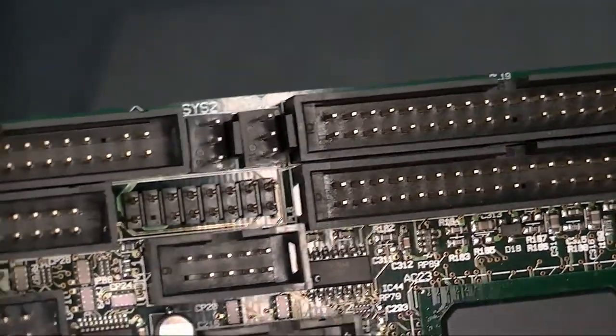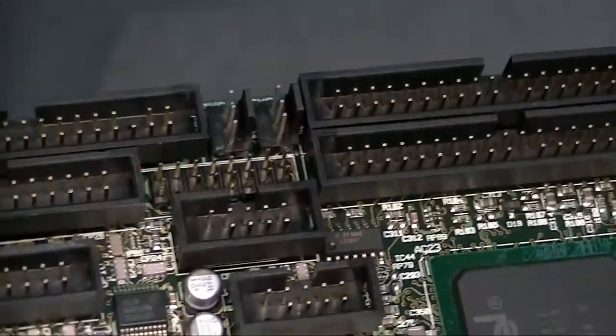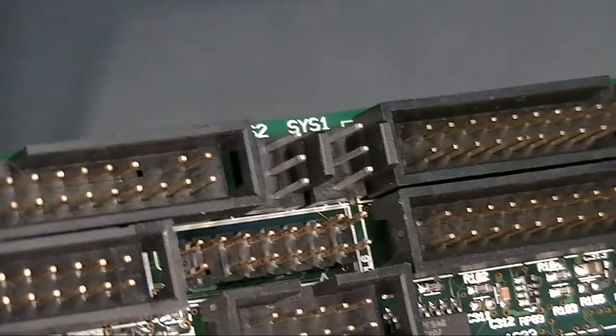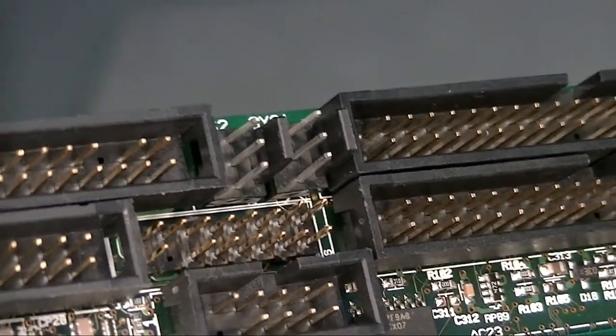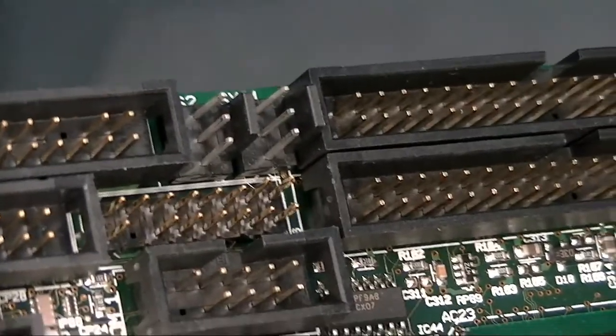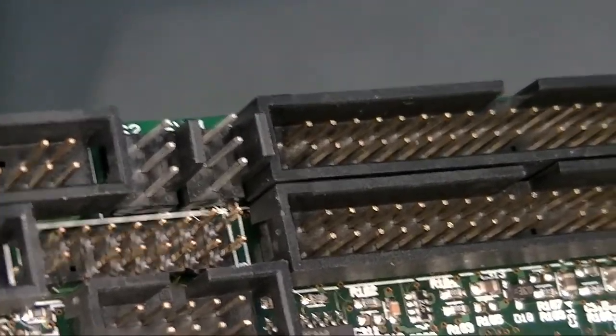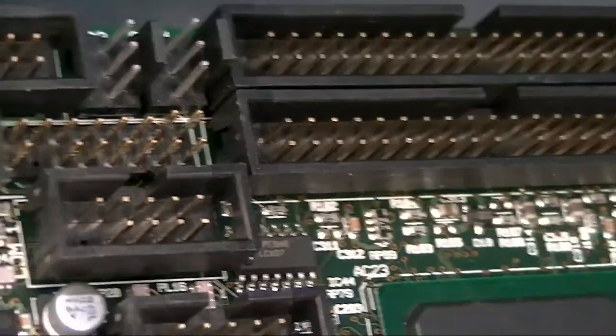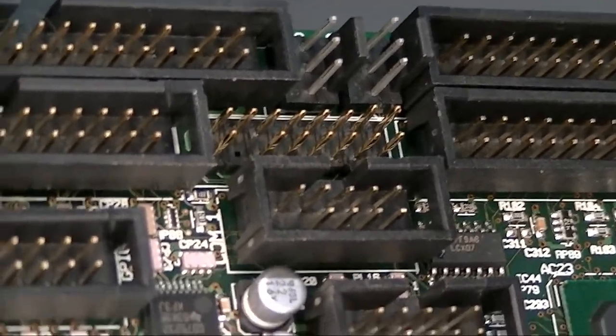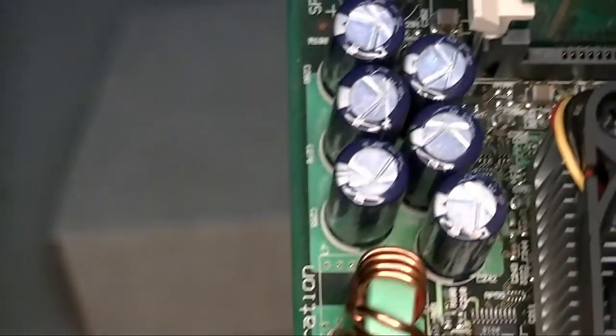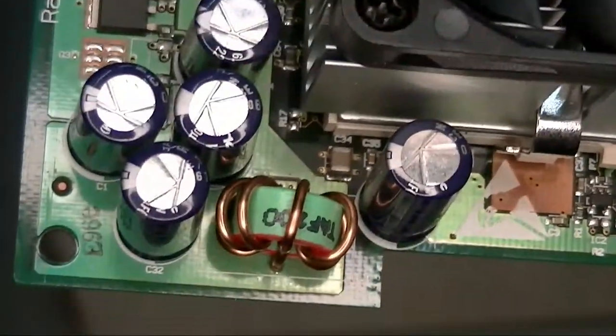We have these sys 1 and sys 2, and I don't know, those are kind of like a fan style connection, CPU fan style, like this one is for having that fan on the CPU and heat sink. So these may be drive power or something else arranged somehow. And they'd be 5 volt on one side, ground on the other side, and 12 volt DC on the other side. And probably not a whole bunch of current. The thought is, you do have the capacitors here on the one end of the board, mainly for just that CPU. But those could be drive power.